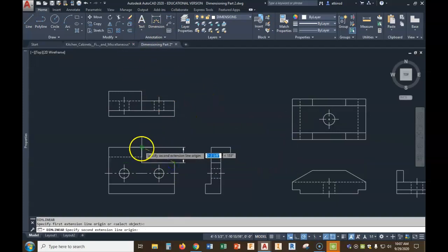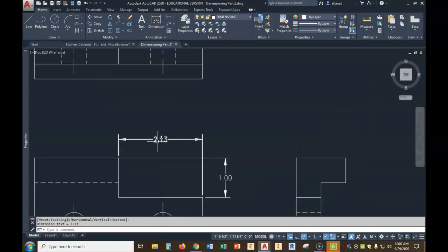Let's go right back into dimension again. Let's go back to this corner again, and let's pull up. Now notice something on this dimension. This is one of these that comes in at 2.13. Well, remember 1/8 is 0.125. So because of that, like 1/8 and 5/8, we fix these numbers. It should be 0.12 and 0.62 for those two dimensions.